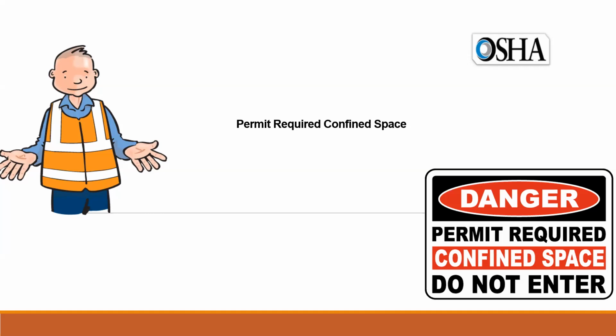Normally permit to work is being issued for a limited duration of time. Maximum we have it for 8 hours, and within 8 hours sometimes you need to have inspections on an hourly basis or 2-hourly basis, depending on the criticality of the task. For example, if you are using the permit in confined space, maybe after every half an hour, after every hour, you have to perform the gas testing.